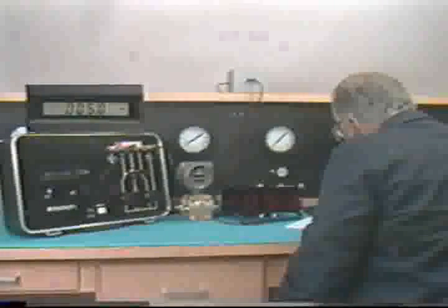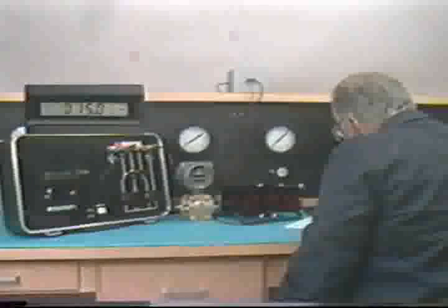The first input value to the transmitter is 5 inches of water. The corresponding output is 5.3 milliamps. At 15 inches of water, the output is 7.5 milliamps. At 50% of span, or 25 inches of water, the output is 9.7 milliamps. Now, with 35 inches of water input, the output is 11.9 milliamps. And the last reliable input value at 90% of span has a corresponding output of 14.1 milliamps.